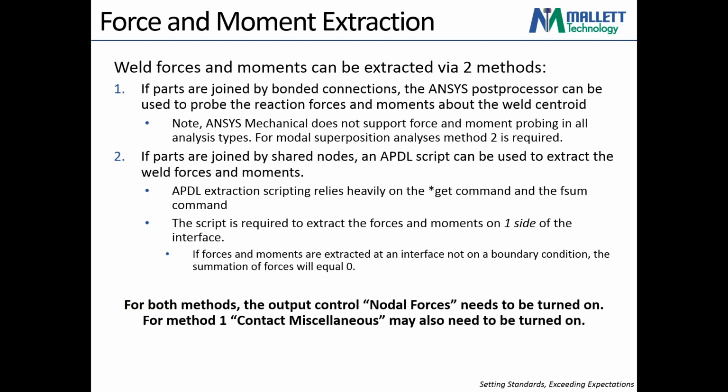The challenge here is ANSYS does support this capability in static structural and transient structural simulations. However, for modal superposition analyses, so that's going to be harmonic analyses or random vibration analyses, that query option is not available.